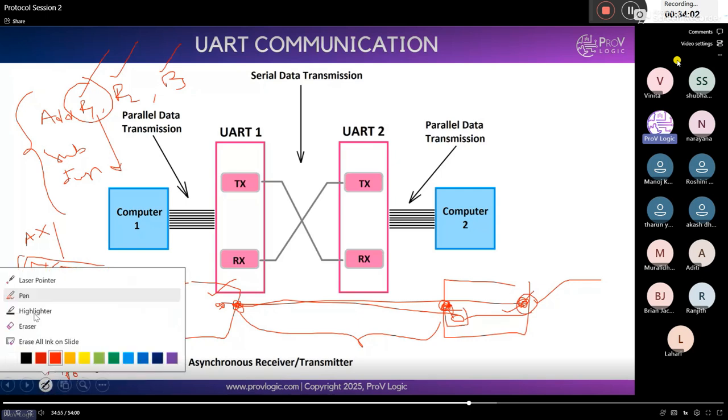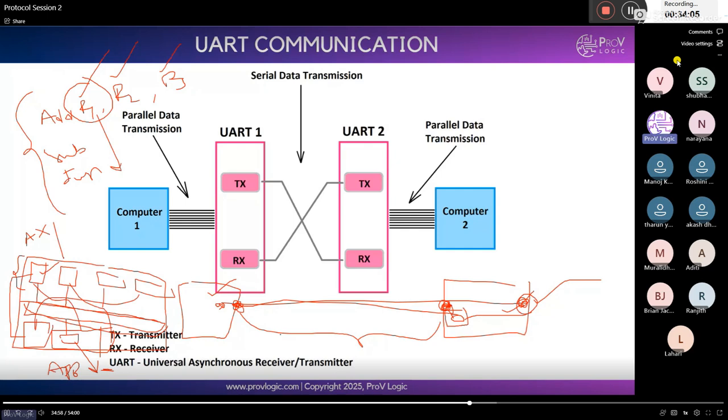Again there will be an interconnect. This side an APB interconnect will be there, and this side an AHB interconnect will be there. And now the handshake will happen. That means in this particular GSM there will be write address, write data, read data, and the processor also has write address, read address, register data, everything. So that's why within the internal chips we mostly have addresses and data, even in APB or AHB, AXI, I2C, SPI, PCI, whatever you take.